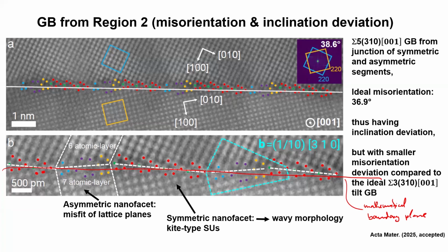And this is also interesting because when you look with more and more high resolution at the grain boundaries in your material, you will see that there is always a tendency for faceting. It could be just very small. The facet length might be so small that you only see it if you go to real high resolution methods with atomic resolution. But the tendency is there, because then this facet can be filled with one structural unit, and that is saving energy. But then there must be another facet, and this must be a different structural unit or an arrangement of different structural units, as shown here.